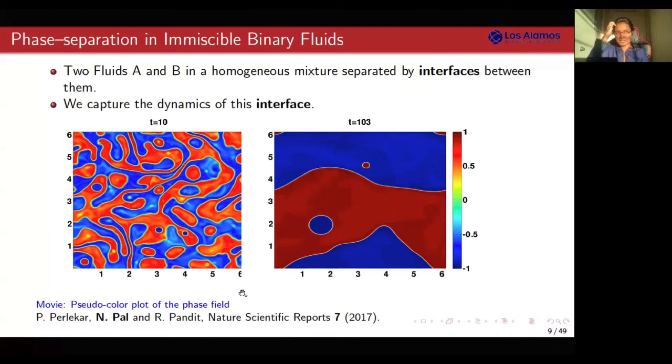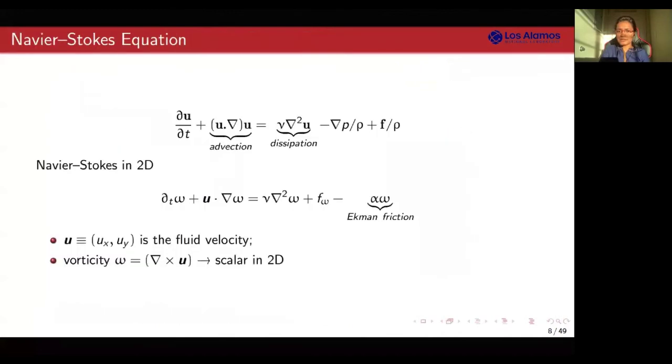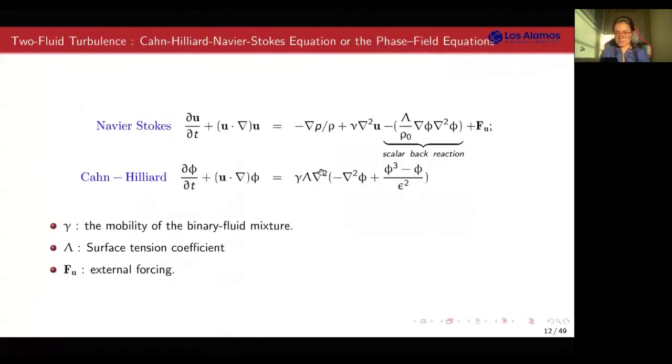Basically, there is a 2D counterpart, and that comes from dimensional analysis of the coupled Cahn-Hilliard Navier-Stokes, because in this case we have to consider that everything is two-dimensional, and so there is a corresponding dimensional analysis, because the energy scaling spectra also changes. It is k to the power -3 in 2D, in the 2D inertial range.